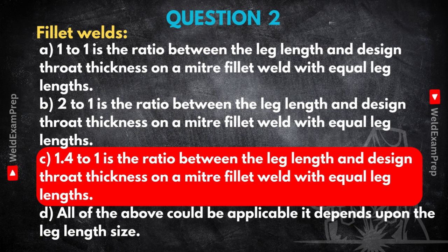Right, that's quite precise. So for an inspector checking welds, how critical is hitting that exact 1.4 ratio? What happens if it's a bit off? Is there a common mistake people make? It's actually very critical. The insight here isn't just the number, but what it represents. Strength. Engineers design welds based on the throat thickness, because that's the effective area carrying the load.